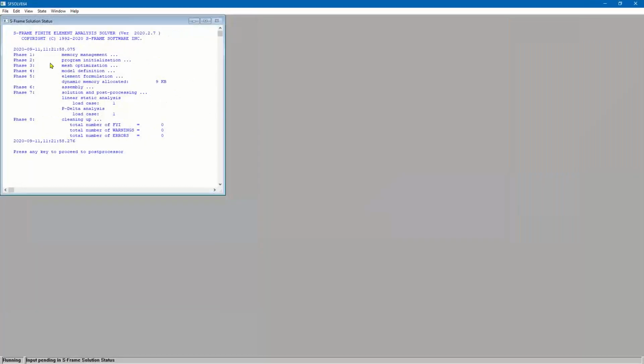And you can see here as we go through the solution trail for the P-Delta static analysis, what happens first is the solver is actually going to do a linear static analysis. Again, what it's doing is it's determining the stress stiffness matrix based off of the stress model that we've already analyzed. And it's using that updated stress stiffness matrix and performing a second P-Delta or linear static analysis on that. And this way we have basically two different analyses showing up here.